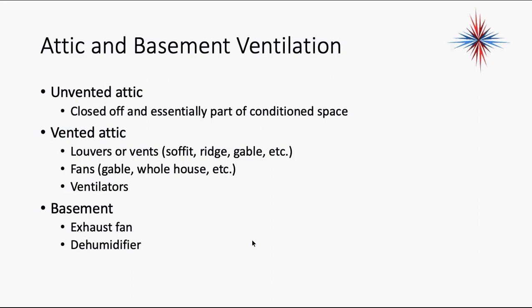Attic and basement ventilation is extremely important. An unvented attic, it's closed off and it's essentially part of the conditioned space. So attics, if they're not vented, you consider them as part of the conditioned space. This is very important when we're talking about load sizing. Now, as far as I know, every state in the country now is requiring vented attics for new construction. I think it's actually part of building code now.